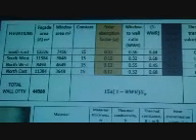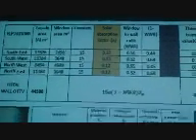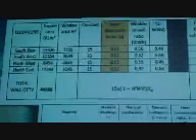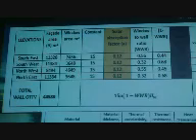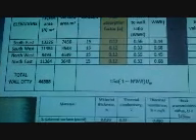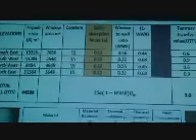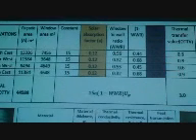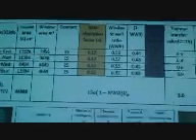Northeast, we assume same with southwest, which is 11,384 for the facade, and for the window area is 3,648. Okay, the formula for OTTV is 15 alpha (1 minus window to wall ratio) times the U value of the wall.